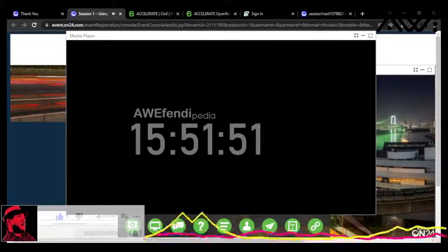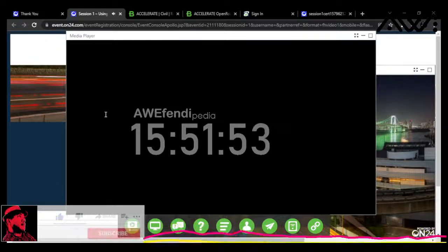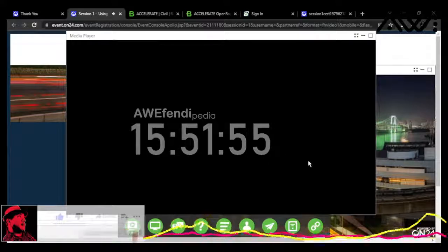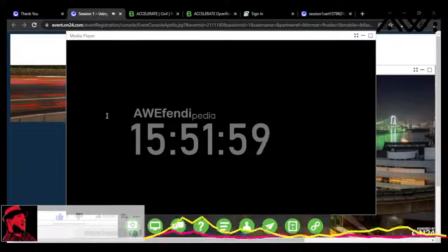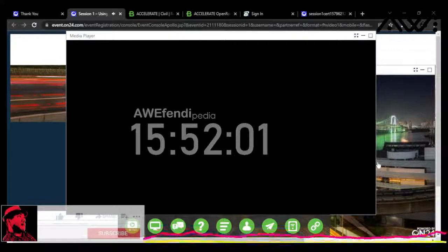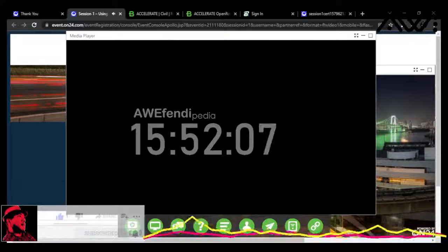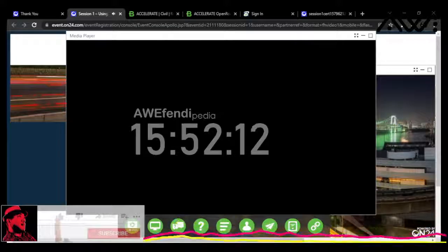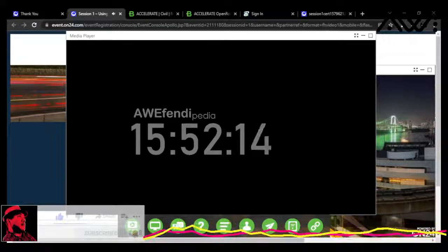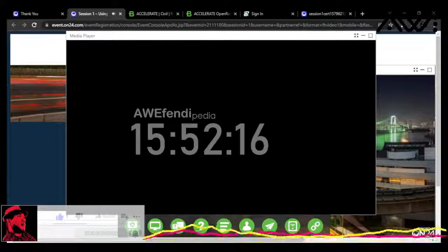So up in the search ribbon, I'm going to type in coordinate in order to get my coordinate systems command, and I'm going to click on that. You'll see this is the current coordinate system. We're going to switch that over by choosing the From Library button. Hopefully in your organizations you'll have this set up in a seed file, but for the purpose of our class, we just need to make this change real quick.